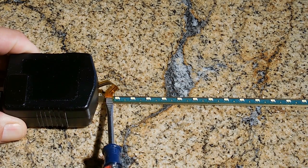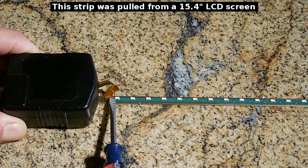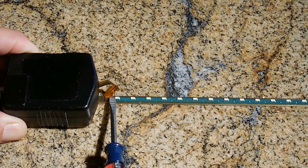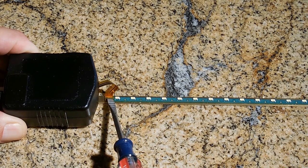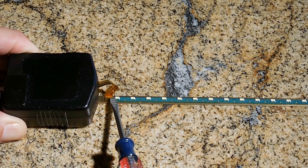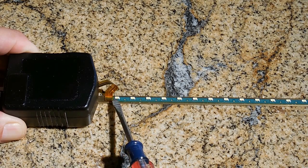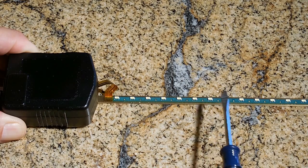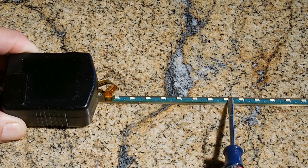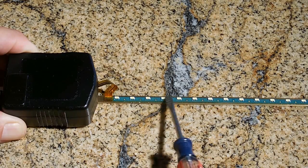On this side of the first LED chip, located right next to where the cable goes in, that is a positive connection. The strip is set up in 4 sets of 8 LEDs. So you have the positive right at the beginning, negative, positive, right? Keeps connecting in series. So you got to connect 8 of them together. So 1, 2, 3, 4, 5, 6, 7, 8. On this side of the 8th is the negative. So you would have your positive here, and your negative would be on the 8th, which is there.